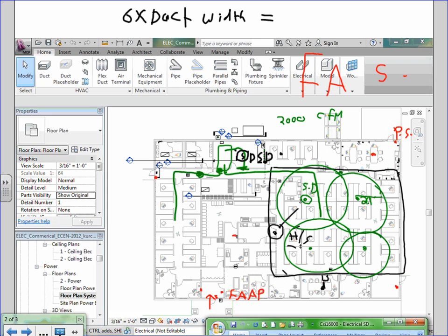So duct smoke detectors are a little bit complicated sometimes, but the moral of the story is that you need one of them, and it's in the mechanical room. So is that 9 feet of duct? In other words, if it comes into the top and it has to hit the floor, most of these things come in with that one. Yeah, it's after any turn. So a straight chunk of 6 feet. Yeah. Okay.